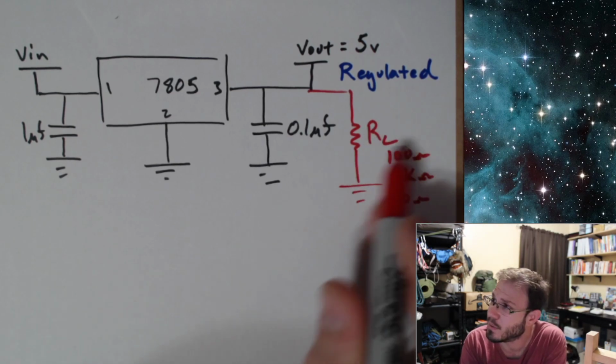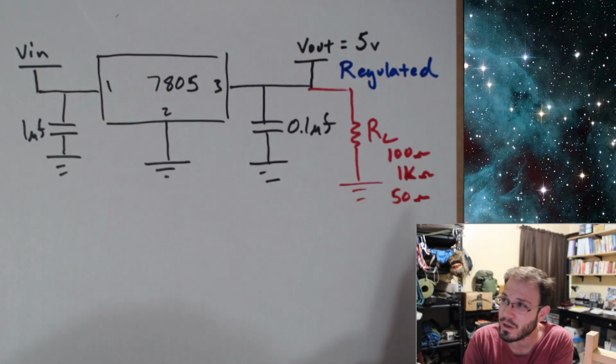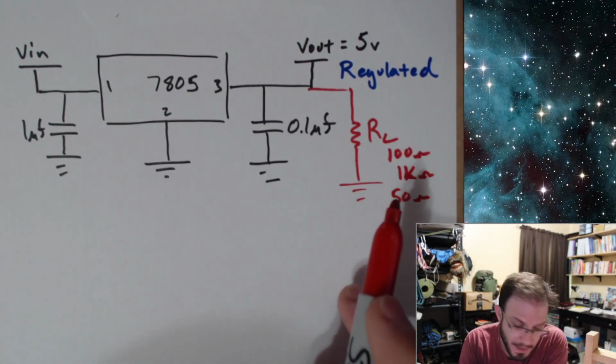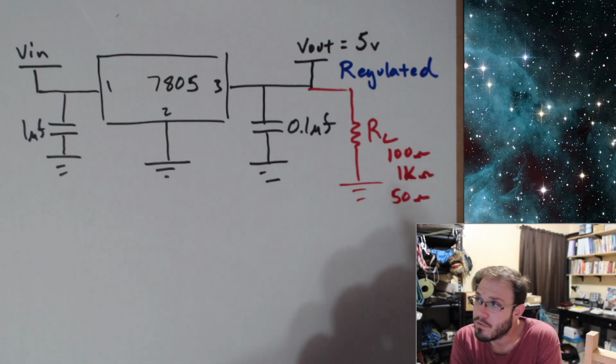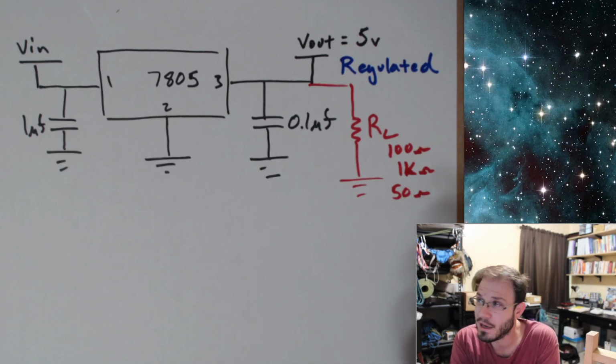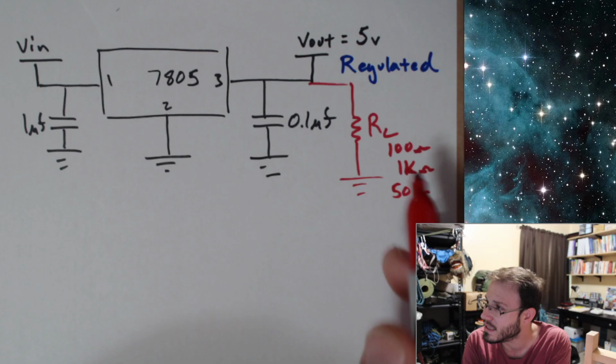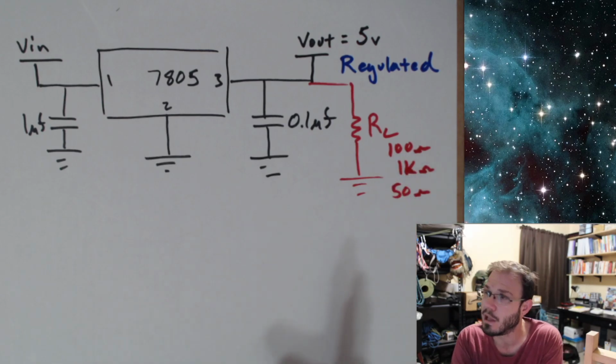It's the size of this resistance that determines everything else that's going on. That's a really important key point to keep in mind, because it's your device that determines how much current it's going to use. And it's ultimately your device that's going to be burning off the power. So the power dissipated is determined by the size of the load.